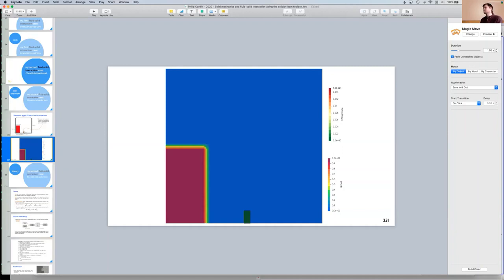Typically in OpenFOAM you use the 6 degree of freedom solver to do rigid body. So you could have 2 different parts and use a 6-DOF fluid solver, and then for your elastic part, use Solids4foam or a similar solver. You may require some coding, I'm guessing. If someone hasn't done something like this before in OpenFOAM, my experience is you may have to get stuck into the code to connect the features yourself.